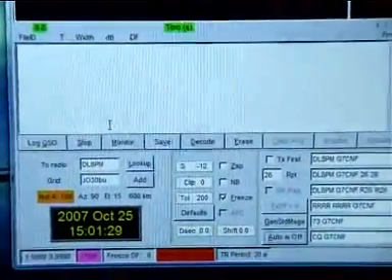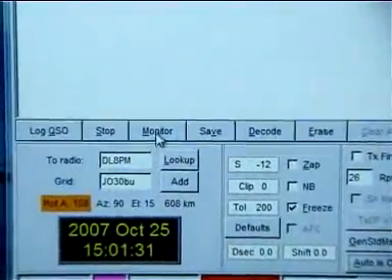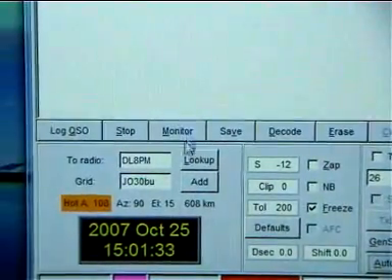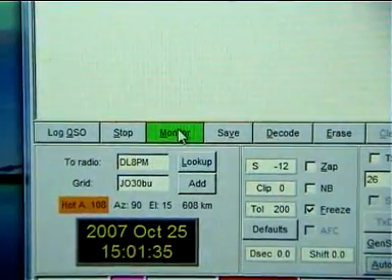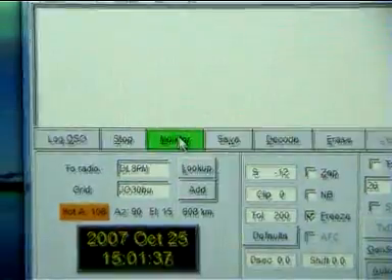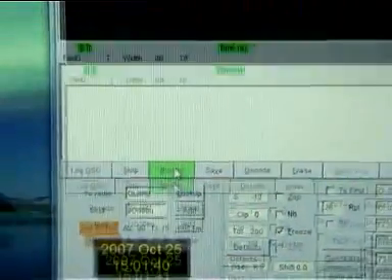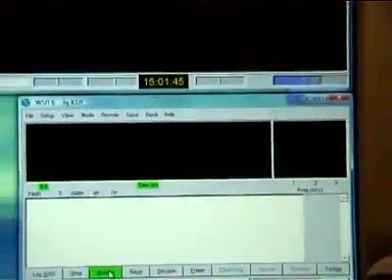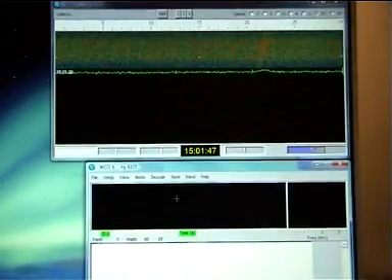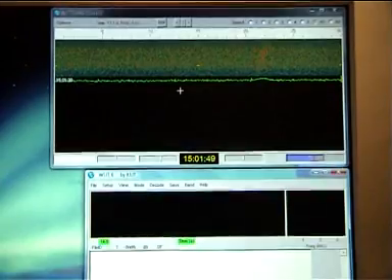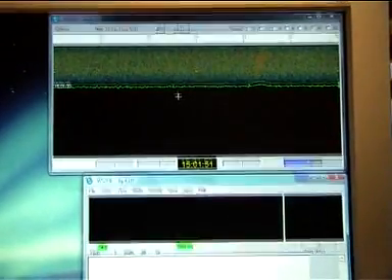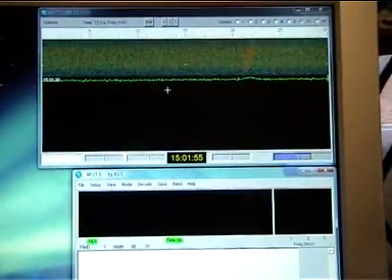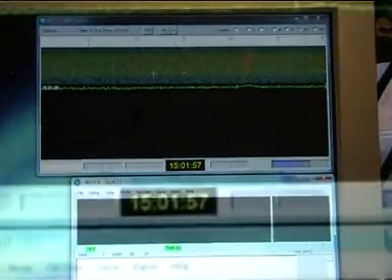Provided the previous sequences have been completed successfully, please go to the monitor button in WSJT and select it. It will turn green, and hopefully WSJT will be taking audio from your radio and receiving. When it does so, you will see some activity appear on Spec JT above. Sometimes you will not always see moving activity until it reaches the end of a period, like so.